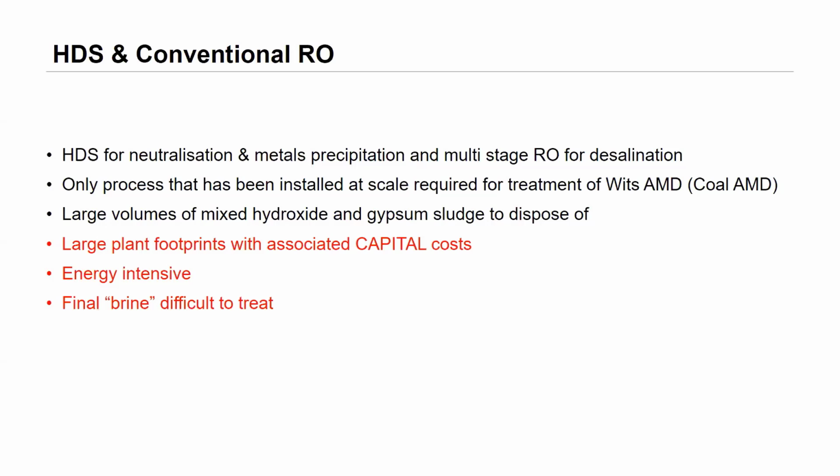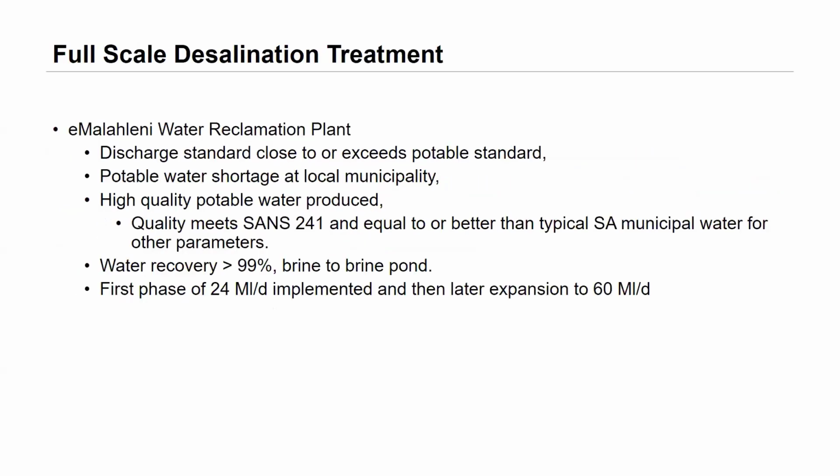the Western Basin area. So two conclusions came up from that: the RO process seemed to have a large footprint in terms of capital cost. That's established, and I think the previous speakers also highlighted that fact. It's also very energy intensive. That's not a secret, and I think both speakers this morning highlighted that fact. But it also generates an extensive amount of brine, which still needs to be disposed of or treated in one way or the other. So nevertheless, I think stakeholders in the country went ahead and implemented the reverse osmosis processes.